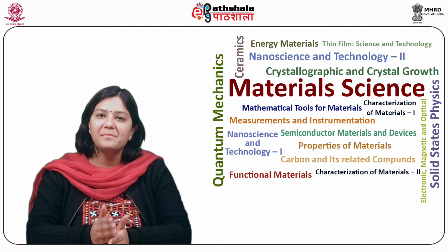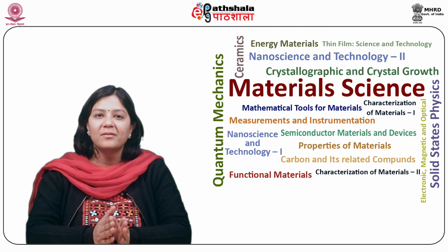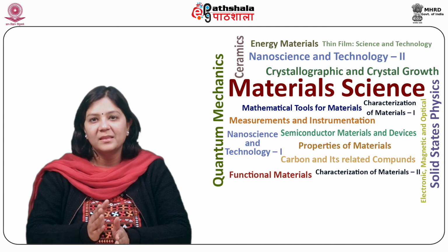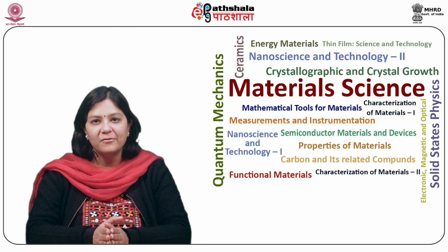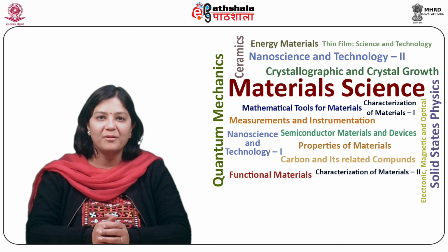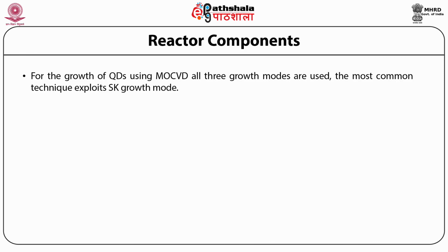This mode of epitaxial crystal growth is known as the Stranski-Krastanov mechanism, named after I. N. Stranski and L. Krastanov, who considered such type of nucleation and crystal growth phenomenon. For the growth of quantum dots using MOCVD, all three growth modes are used. The most common technique exploits the SK growth mode.